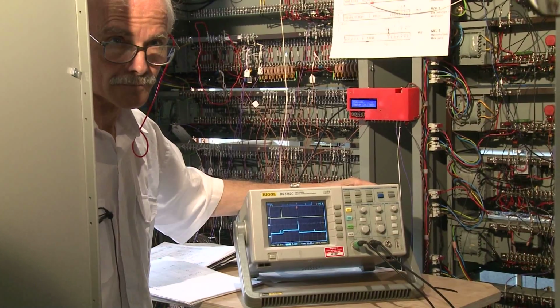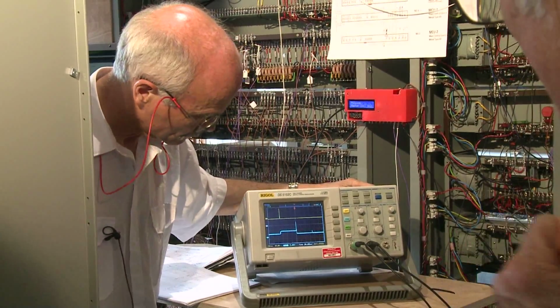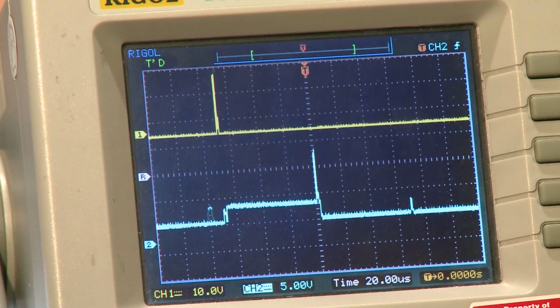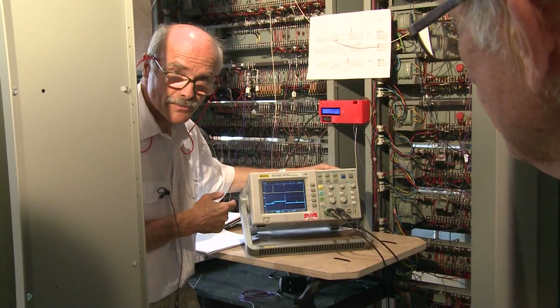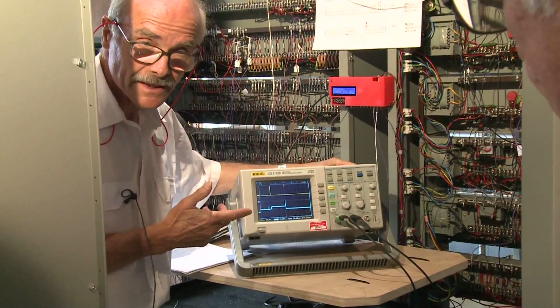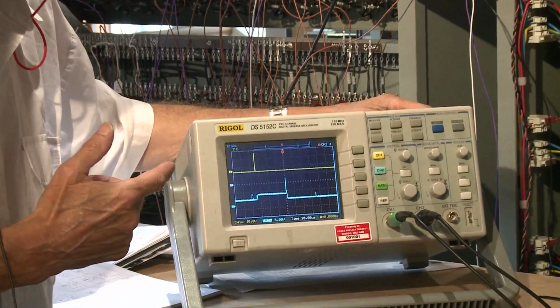So James, you've got a simulated end pulse coming out of Tom's red box, representing what the ALU would have done had we got it here in these empty racks. Can you tell me what that end pulse does in the MCU? The end pulse instructs the MCU that the previous instruction has been completed and the system is ready for finding the next instruction in memory.